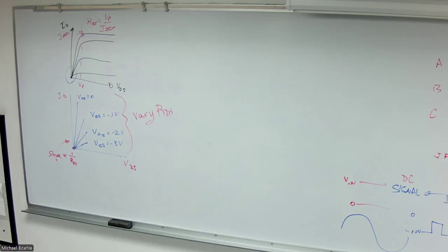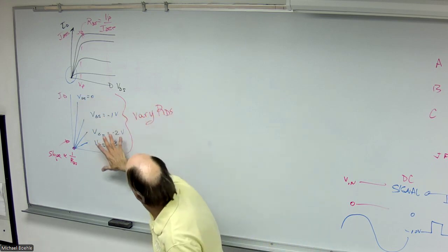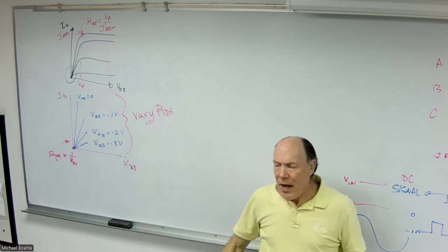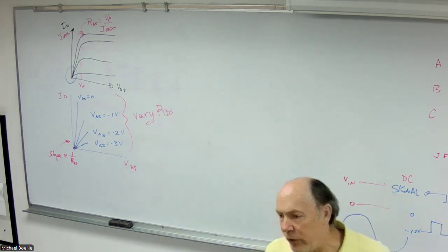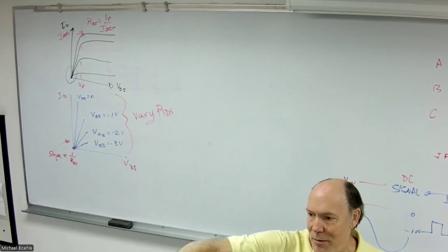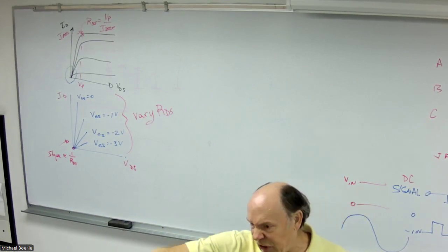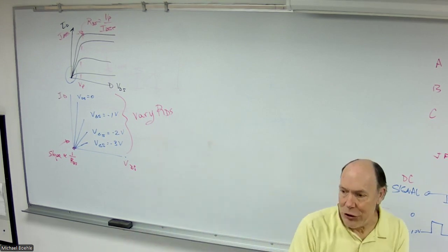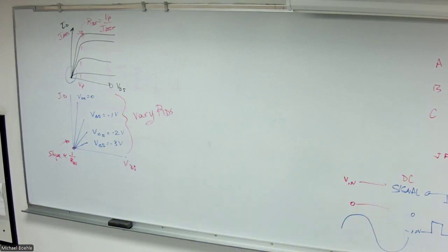So a voltage controlled resistance. We are quite literally using an input voltage to change resistance. We're used to having to do what to change resistance, right? All our potentiometers, you got to grab a knob and turn it. That's a physical input. Now I have the ability to use an actual voltage to change it.